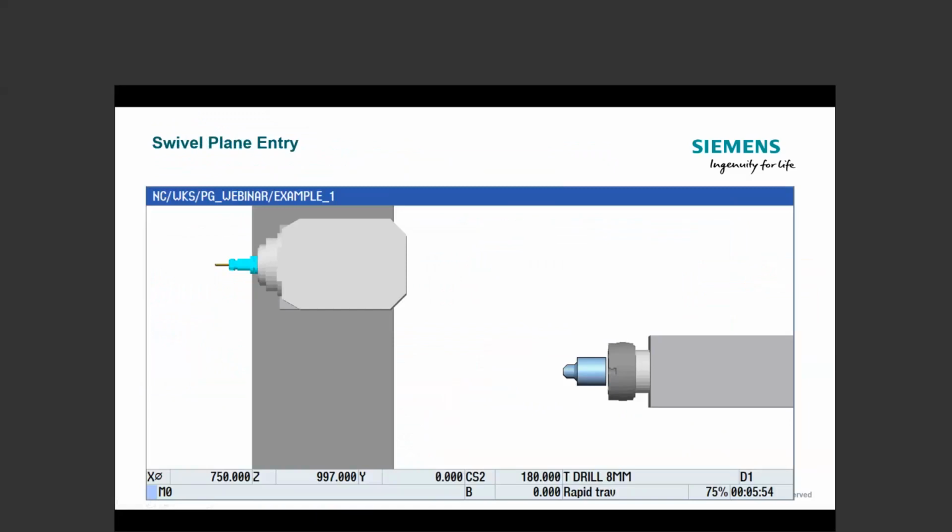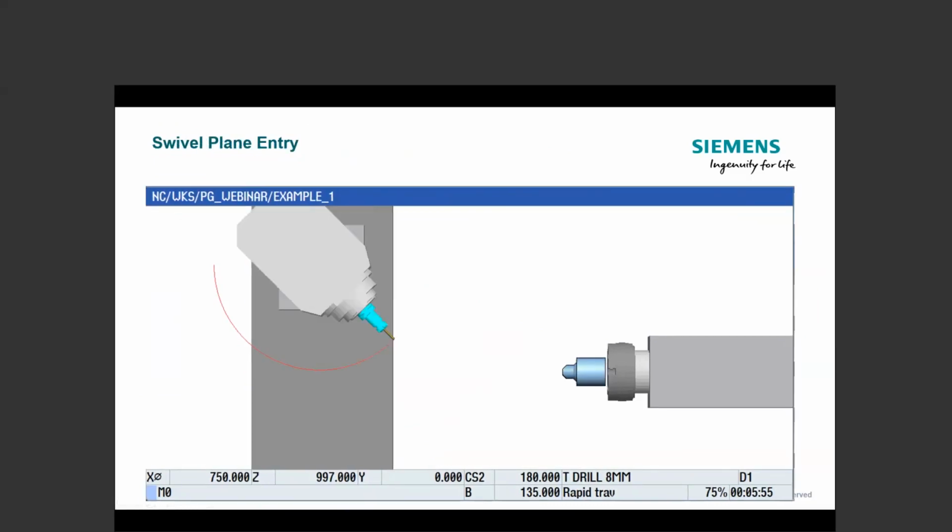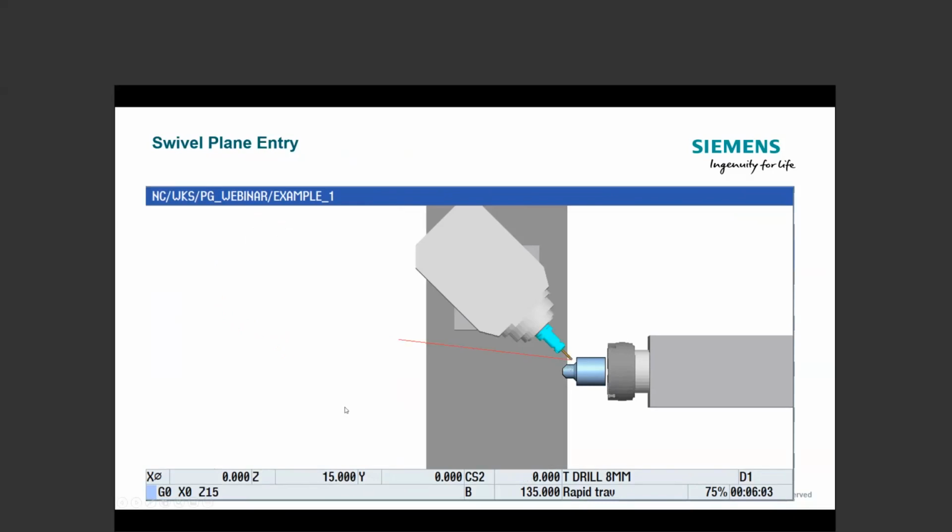So here, let's say I position up at that super location. Well, as I swing, this is not dynamic, as it doesn't have TCP command functionality on. So you want to always be careful when you end up at your final orientation to make sure that the tooltip is obviously above the part. Because the last thing I would want would be to be approaching from down below.